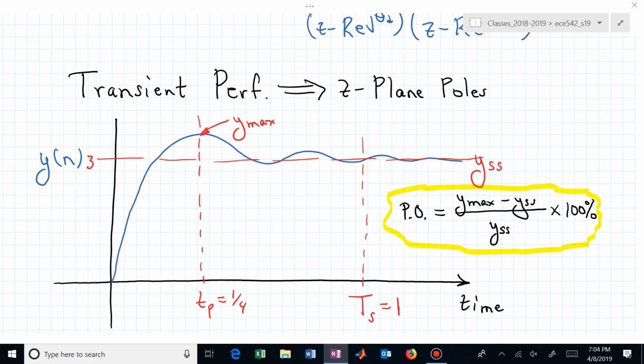You can find when you get within 1%, and some of these are subjective. You're going to have to just infer what that time is on the appropriate axis. If it is the stair-step pattern, you need to count those steps to figure out when it peaks, and just be clear that sometimes in those steps the system may not start responding for more than one sample period. If you had a pole zero excess of 2, you may actually be locked at 0 for 2 sample periods before you go up.